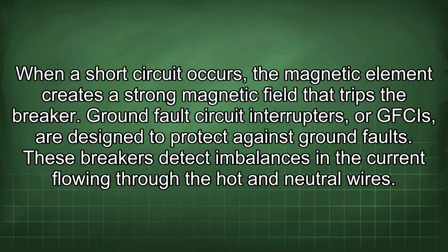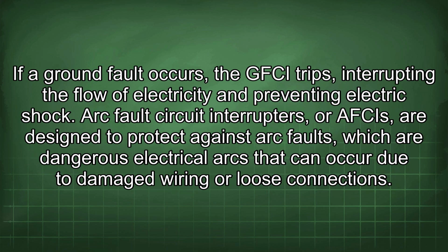Ground fault circuit interrupters, or GFCIs, are designed to protect against ground faults. These breakers detect imbalances in the current flowing through the hot and neutral wires. If a ground fault occurs, the GFCI trips, interrupting the flow of electricity and preventing electric shock.